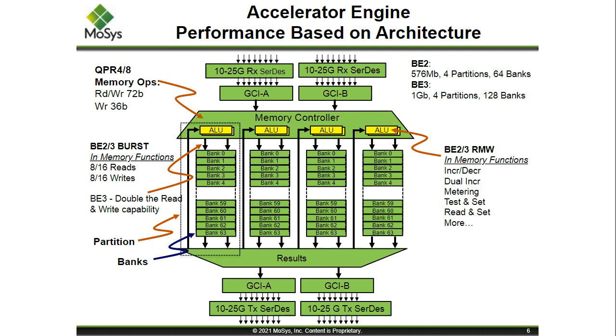What we're trying to point out there is that what also is built into this device is the ability to do multiple operations concurrently. So this is pointing out for the smaller device, we can do 2 writes, and the bottom shows 2 reads occurring simultaneously within each partition. So that means in the smaller device, we can do in 1 memory cycle, 1 TRC, 8 writes and 8 reads because of the structure of this device. Again, allowing for very high bandwidth.